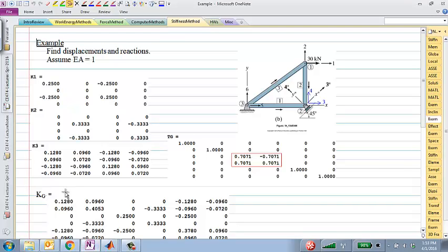As it's mentioned in the handout, I'm not going through those same steps as I went through last time, showing you how each one of these matrices is constructed. I hope you understand that now that in this truss there are three elements. So if you remember when we went through that loop over elements, it will go to the first element and first it will compute what? For each element, you remember what we did first? We computed the element stiffness matrix in the local coordinate system, right?